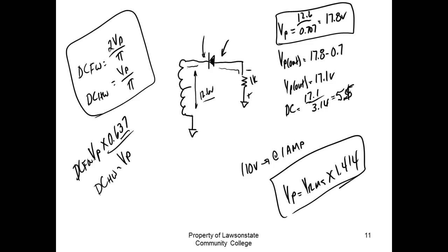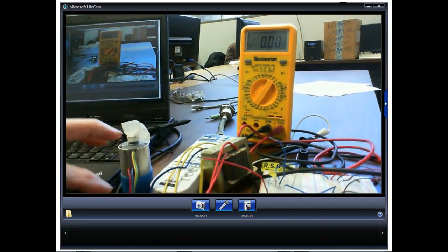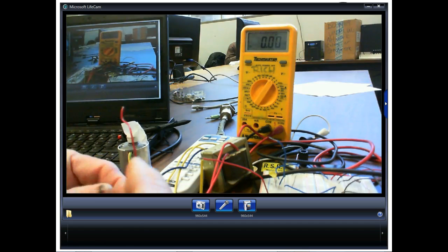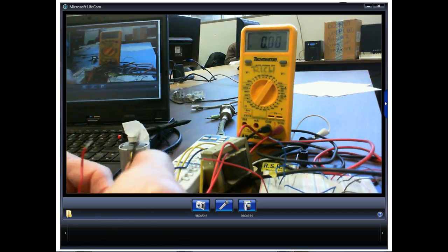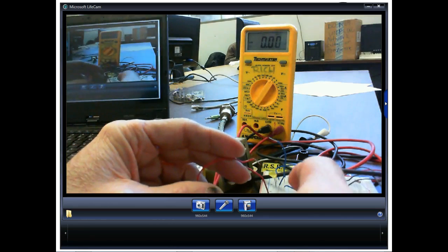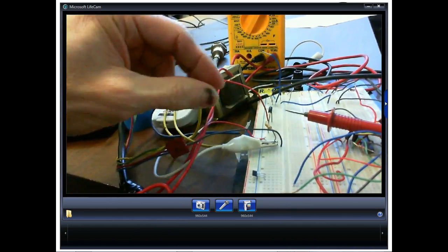And of course, we came up here and we hooked up a motor to it. Now, what the DC polarity on a motor does is it determines the direction of rotation. That's what it does on a DC motor. So this is our common. We've established this as our common. Okay. And then I'm going to come up here and just put my motor across this.